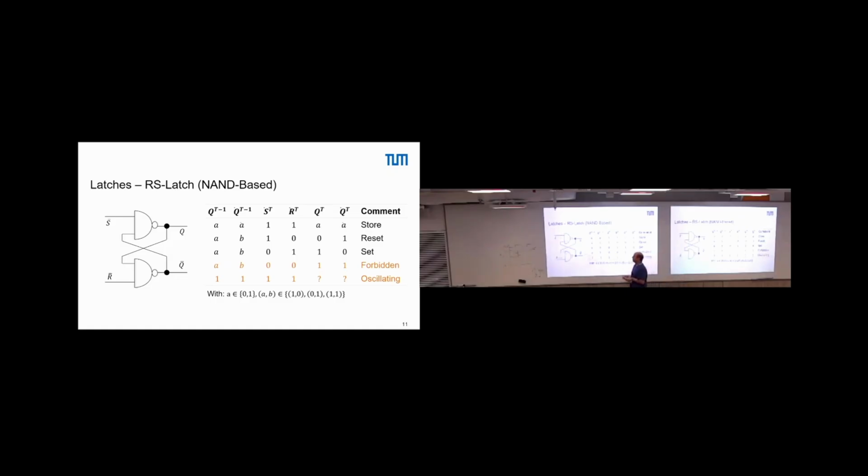So this is a case where we effectively drive our circuit for a longer time in a metastable state. And, well, if we are unlucky, we destroy the circuit because we burn a lot of power, we make it hot, and it's destroyed. Yeah? Not so nice. Benefit of these latches is it's very small, and you do not depend on the clock, so you can do something clock-independent, asynchronous.